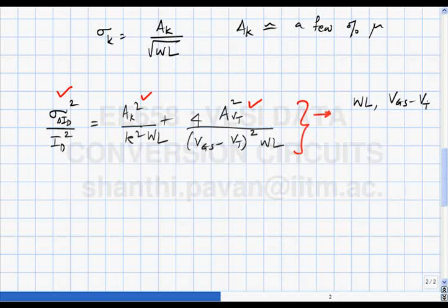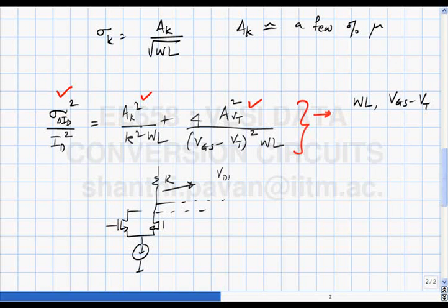You please note that you have to fit the entire current source, which is the basic transistor, the cascode, the switch, as well as all these current sources go into a single load resistor. So the peak output voltage, the lowest voltage at the output is nothing but VDD minus, so you have a whole bunch of these guys. The lowest voltage here is nothing but VDD minus 2 power n times I times R.